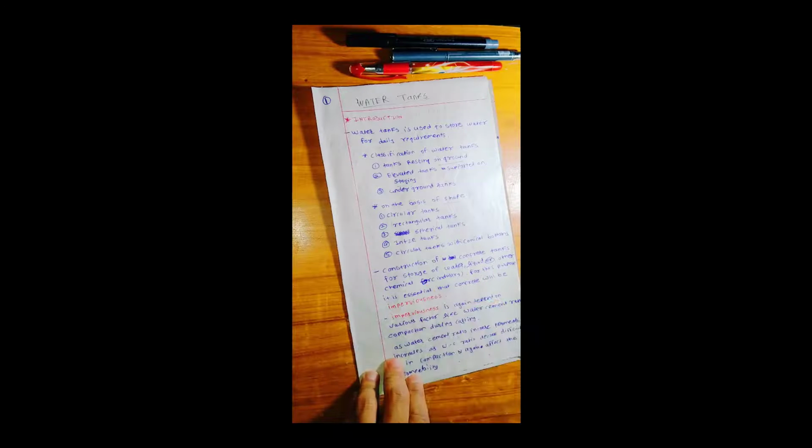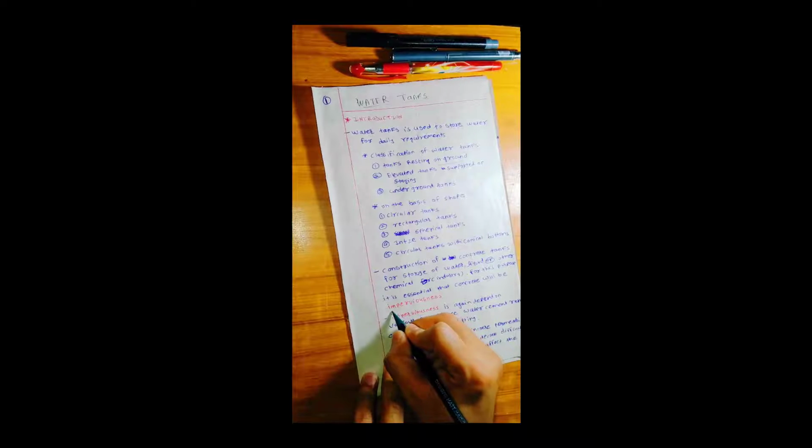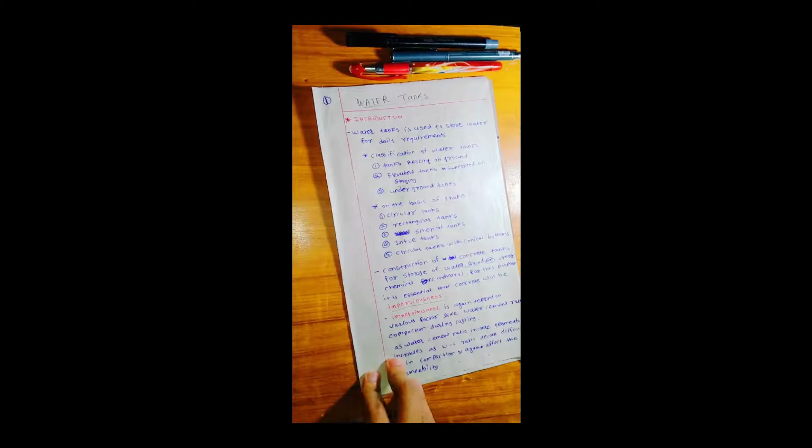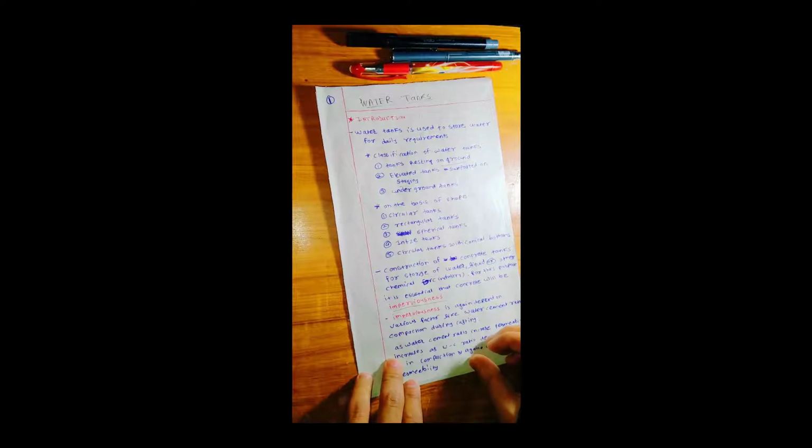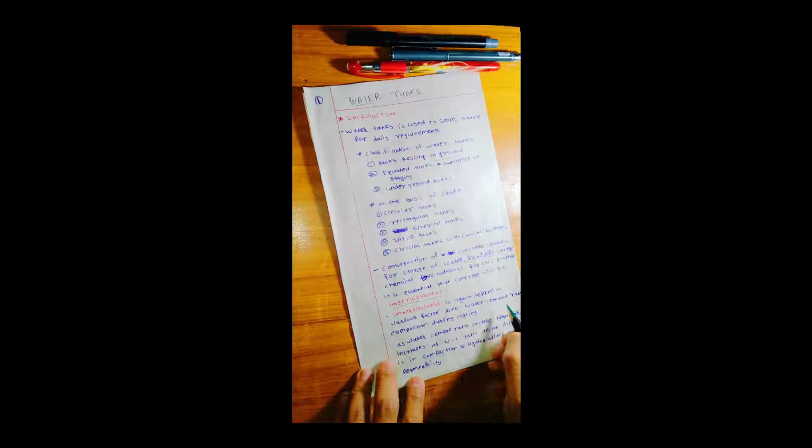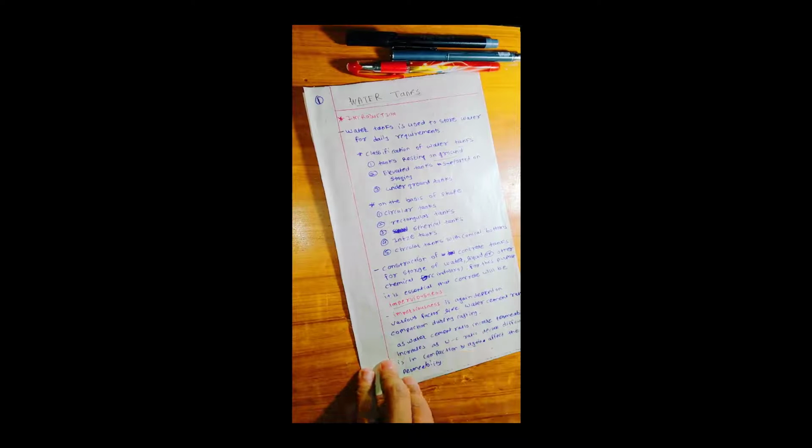Now, construction of concrete tanks for storing water, liquid, or some chemicals. For these purposes the concrete is essential, and the concrete should be impervious. Imperviousness means zero leakage. Imperviousness depends on various factors like water cement ratio and compaction during casting.